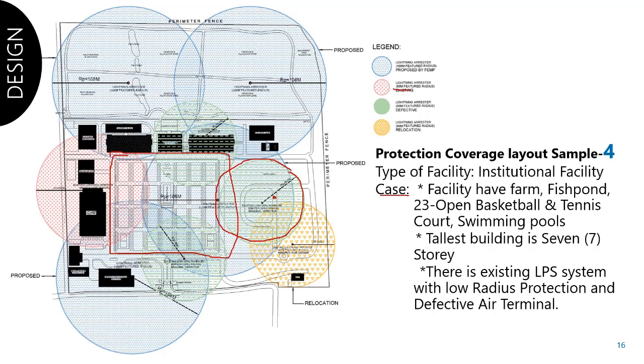That's why we have here, if you will notice, one in our design for this facility, 2, then 3, then 4, then this one is already adjusted, that's 5, and another here to cover, so that's 6, with a 106 lightning protection radius. That's the incident that happened here, and that's why it came up with too much umbrella or overlapping design.